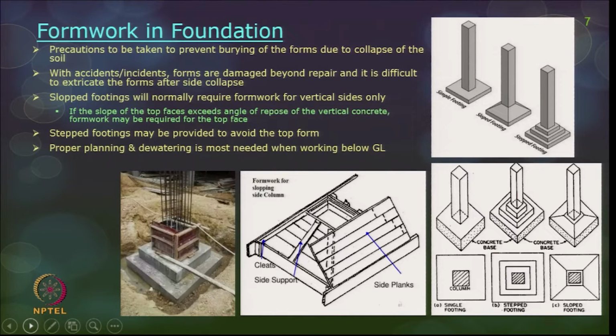Precautions should be taken to prevent burying of forms due to the collapse of the soil. Generally, formwork need not take too much precaution when it comes to foundations. Only the strength aspects are generally seen. Otherwise, for other formwork, the neatness of the structure also depends on the quality of formwork, but when you talk about foundations, it is not too much of a worry for any contractor.